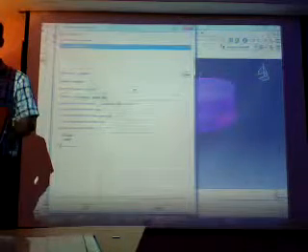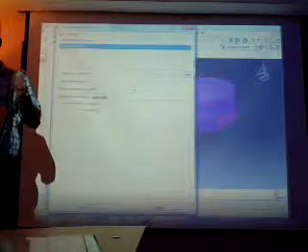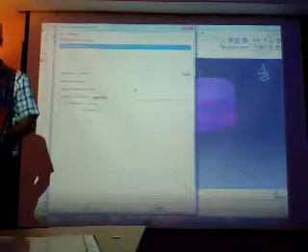And also for sticking friction, if you want to define sticking friction, you can define your shear stress here. Here you can see it defined as no limit. You can specify this according to your yield stress, dividing by radical 3 if you are going to use von Mises, or dividing by 2 if you are going to use Tresca.